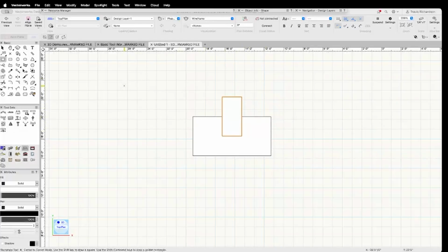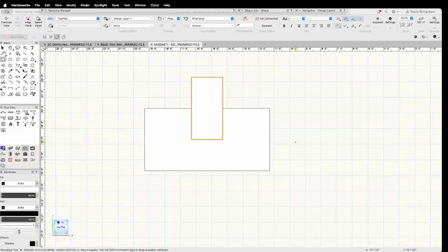The third mode that we're going to look at is the midpoint to corner mode. And for this, I'm going to establish a new smart point that we haven't seen before. So I'm going to come to the bottom right corner of the rectangle I just drew and grab that smart point. I'm going to move my mouse over and get the center right smart point of the first rectangle. And now I have this new tick mark that's right in the middle of those 2 smart points. So that's where I actually want to start my rectangle. So I'm going to click there and start it.